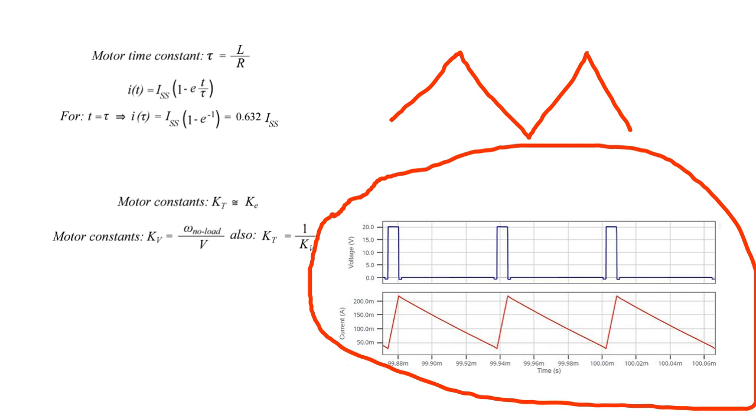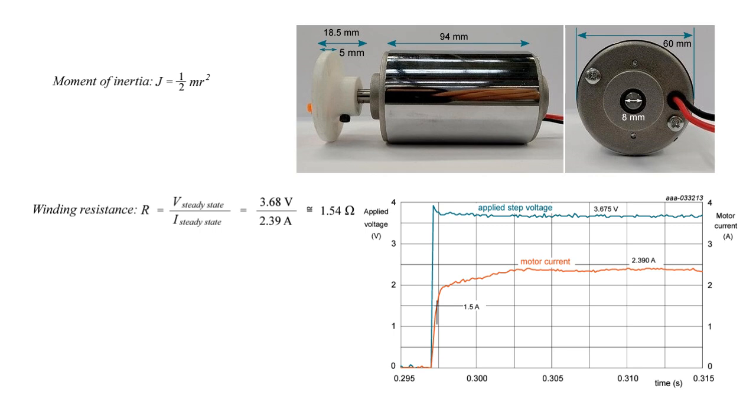Okay, for example, moment of inertia. If your moment of inertia is very high, the starting current value of your motor drive system will be very high. For example, your rated current value is 5 ampere, and at starting time you will measure 30 ampere, 40 ampere, for example, if you have a high moment of inertia. Okay, so we are using an oscilloscope in our drive applications. This is the typical power value.